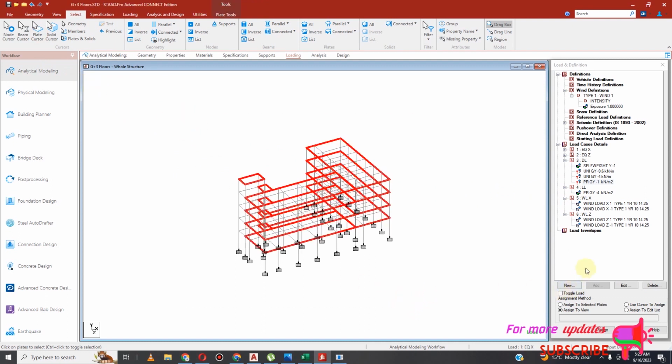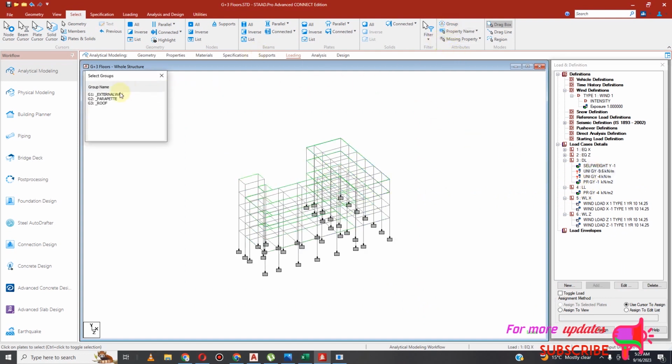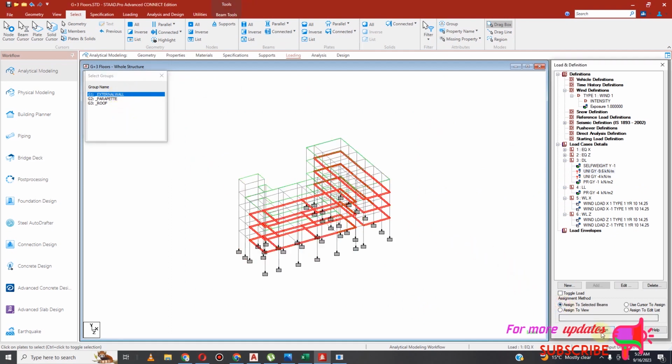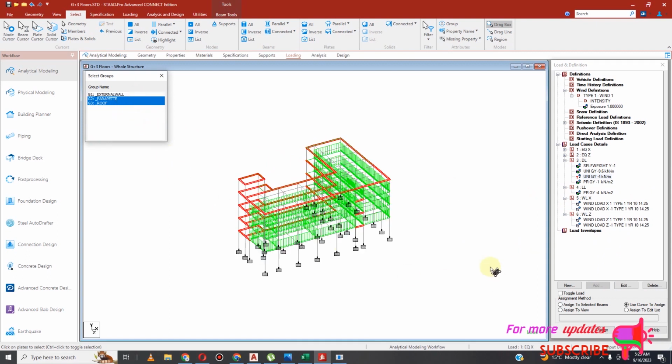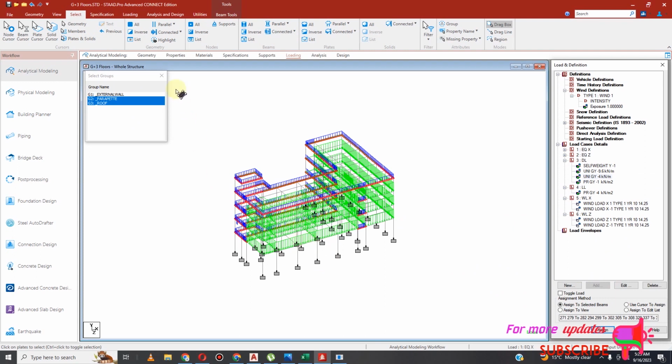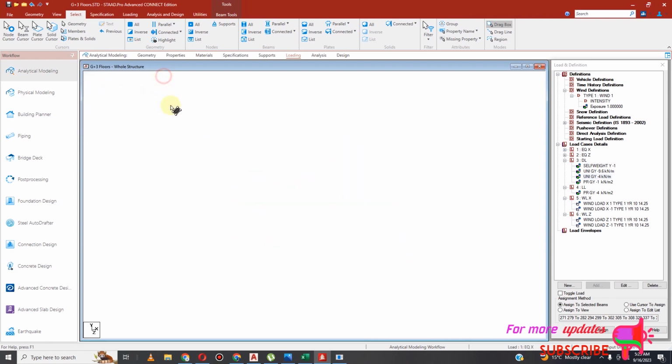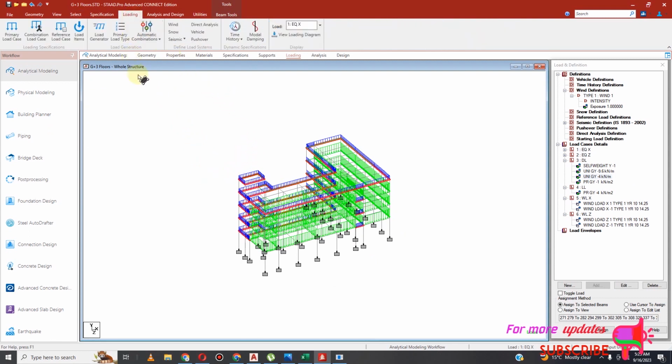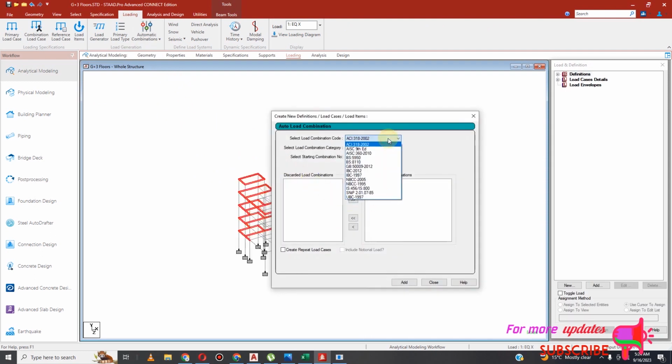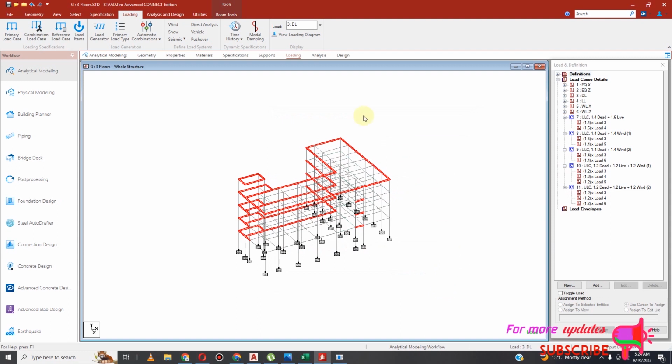So let's first assign the plate loads. So remember 9.6 was for external wall, so we'll go to group, external wall, then assign. Then -4 was for our parapet and the roof. Select external, assign yes. So then we save in case we will not lose everything after all that work. So we add load combination BS8110, generate, then add, then close, then go to analysis.